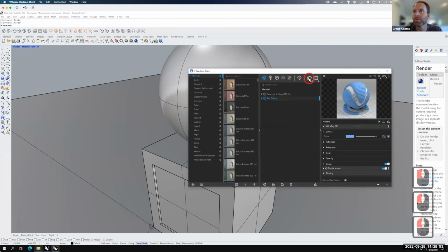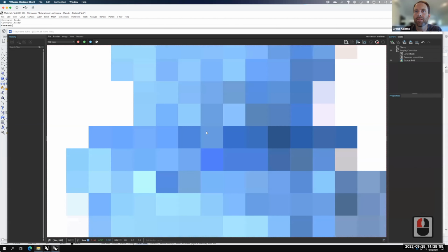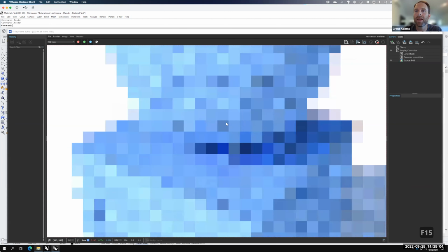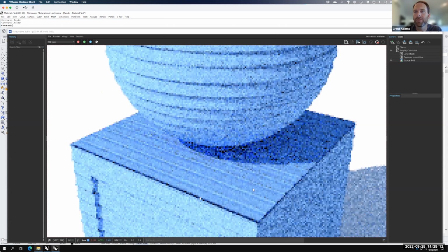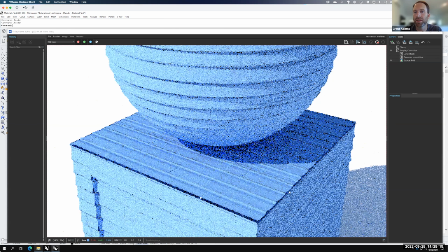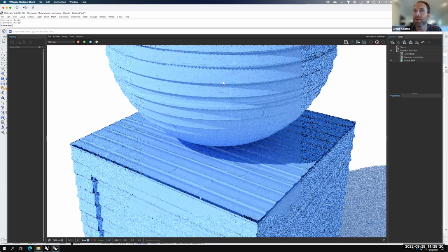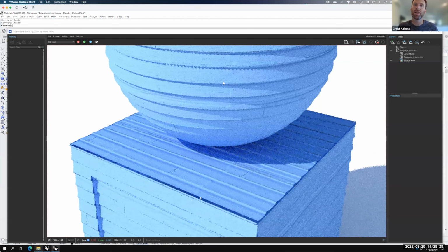Well, I could then stop my render, start my render again. And instead of having the red siding, where I'm using the image as a background, we could add the blue to it as a light blue, and we'd still get the texture on it and our displacement where we have our little lips, and it looks like it's siding, but this time it's blue. So once I've created this and I have the bump and I have the texture applied to it, I could actually step away and not even have the original photograph anymore.